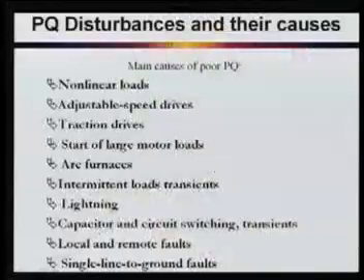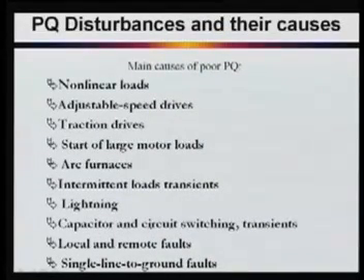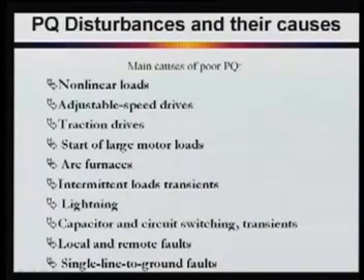If you are starting a large motor, what will happen? They require a huge inrush current that is rich in harmonics, and when this sudden huge current flows, it creates a lot of power quality problems in your supply system. Arc furnaces also introduce power quality problems.